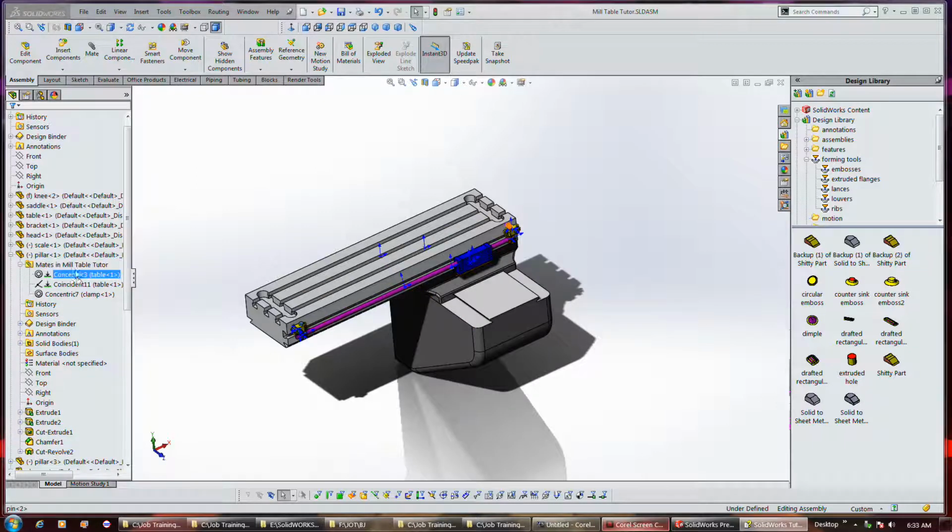Now like in the mates in this pillar object, if you highlight them, this little icon here means these are in the path to ground, so that means these 2 are primarily responsible for holding the object stationary relative to our base object, I suppose is what they mean.